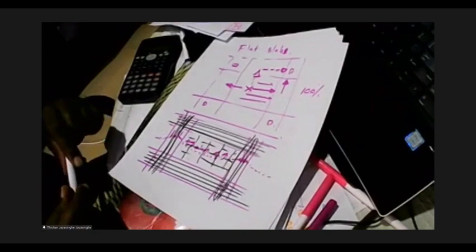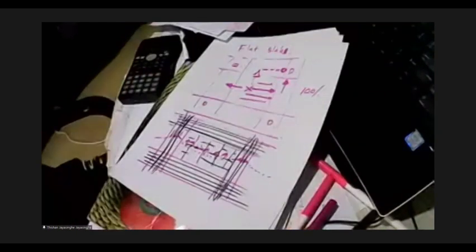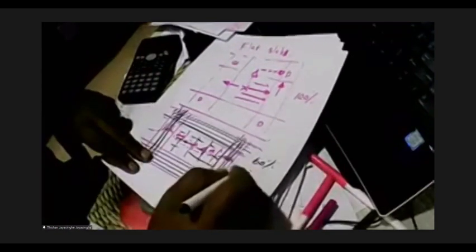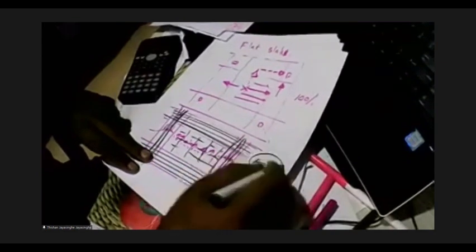Bring in the load. So the column strips will be carrying a higher load, middle strips will be carrying a lower load. The deflection is also controlled by the longer span, not by the shorter span. So this is what people thought initially. Then they started designing this way. And they said, okay, let's say the shorter span carries 60% of the load, the longer span carries 40% of the load. Go for some combination.